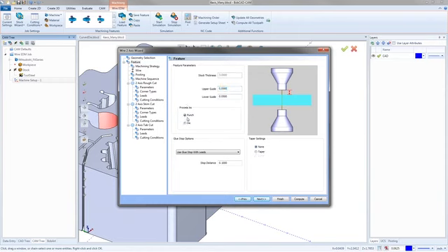Right here, you have process as a punch or a die. So you can see when you process as a punch, you can put a taper on it, but because you're processing a punch, which is an outside cut, you lose the land and taper. So you've got punch and die. So I did have it right. So the die should be always when you're doing an inside cut or a 2-axis inside, and then the punch is going to be for your outside cuts. So you could really tell the difference because we have a land and taper. I can't put a land and taper on the outside. So I'm going to process this as it doesn't matter.